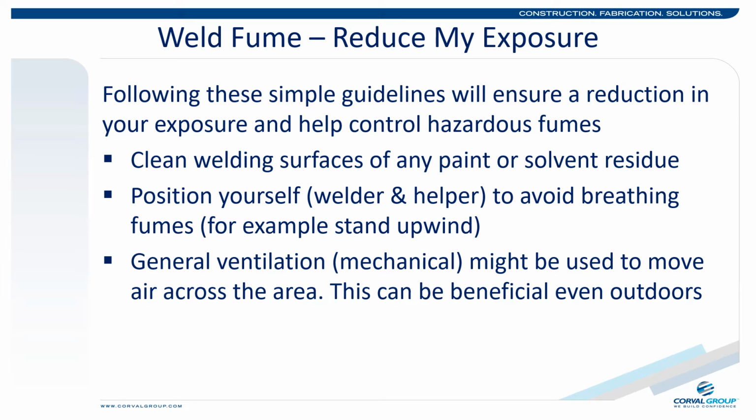There are a number of things that can be done to reduce your exposure to weld fume. Make sure that the welding surfaces are free of any paints or solvent residue. Pay attention to your body position. Identify the flow of the fume and stand upwind when possible.